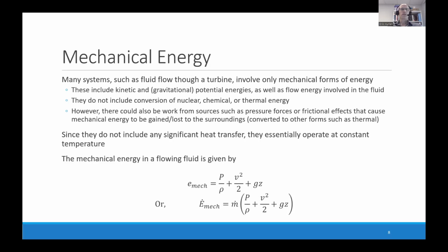In addition to this, we also often use rates of energy transfer. This is how the energy is changing per unit time, so E divided by t. This is also equal to the specific energy, little e, times the mass flow rate, m dot, which is equal to mass over time. Note that rates are usually denoted by dots, as seen here.